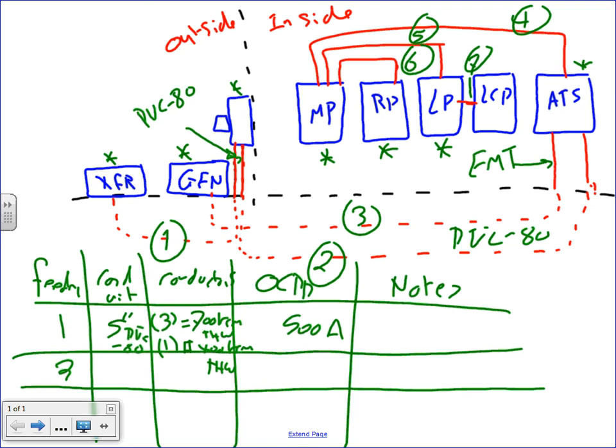PVC above ground, EMT above ground, it will last, but eventually it will rust. Oh, yeah. Chad, how about this? I was at a hotel a few months ago. We were in the pool, and they had RMC going, quite a few different runs, and they were rusting. This is called a highly corrosive environment. Yep. That's a good application where you can use PVC.